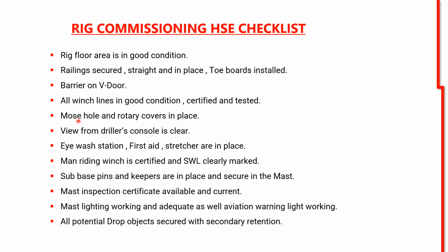It's mouse, M-O-U-S-E. Mouse hole and rotary covers in place. What I said in the first line is the same thing here. When the mouse hole is not being used, or if the well has no pipe, at that time the well hole should be covered and the mouse hole should be covered, so that it can save other people from falling, or any tools or equipment from falling. There shouldn't be any chance for a fall or trip.